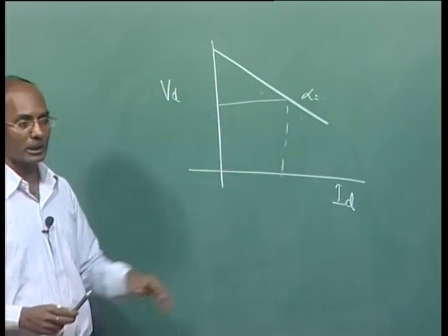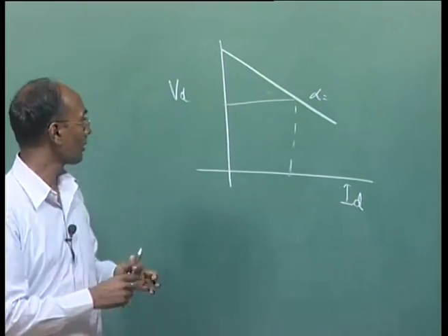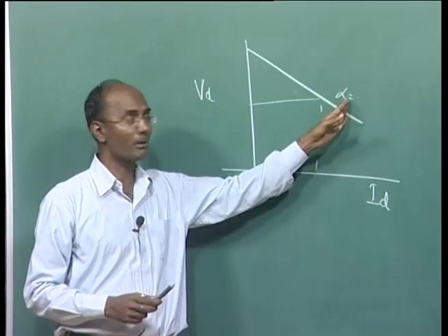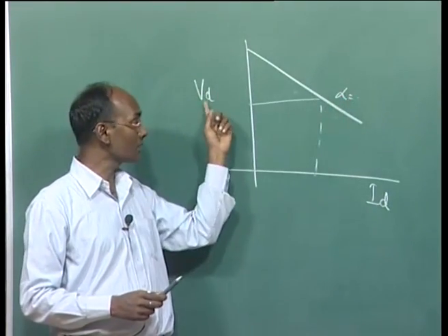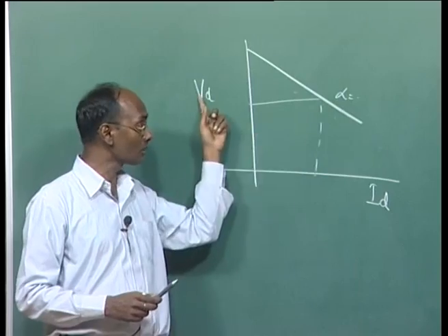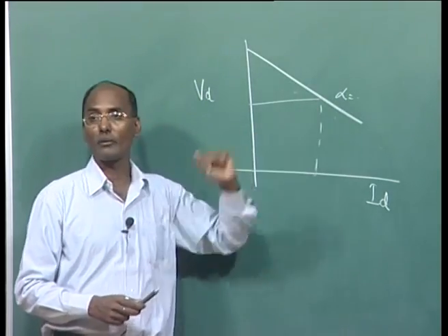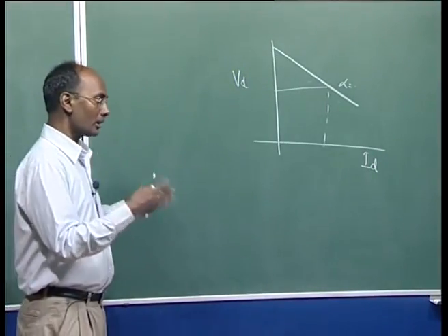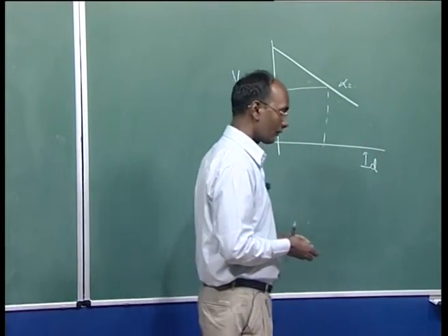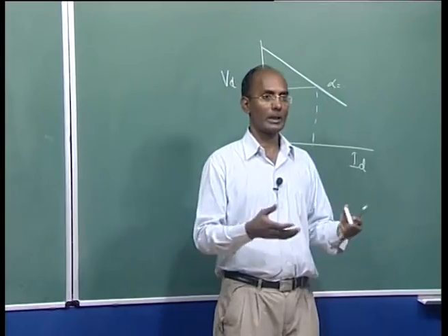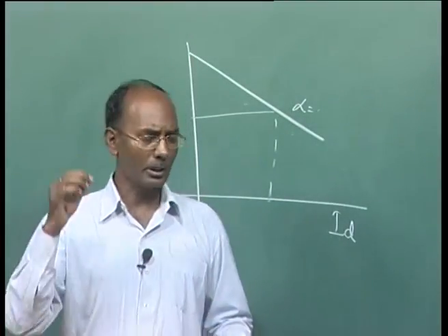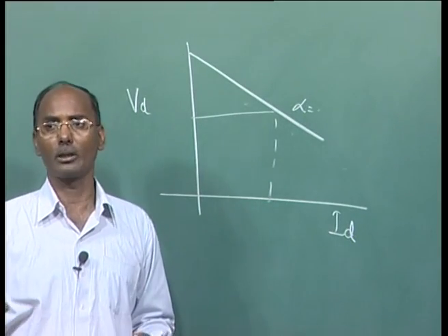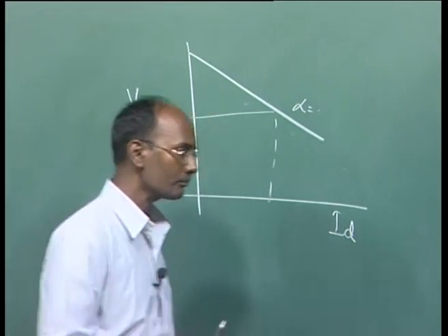So, with the help of the chart, we can get what is your voltage and what is your DC current for a given value of alpha. Or if the voltage and current are known, then you can find what will be the value of alpha. So the reverse is also true, meaning it avoids the calculation, where there are sine, cos, etc. Directly knowing this value, you can find what is the actual operation mode of your converter circuit.